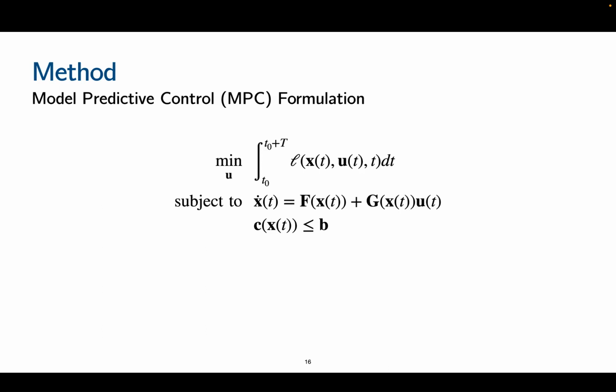Since training is performed offline, the computational cost of using a model predictive controller can be mitigated by using simulation environments or more computational resources than during inference. And once the controller is fully learned, during inference time, only the learned CBF QP controller will be utilized.